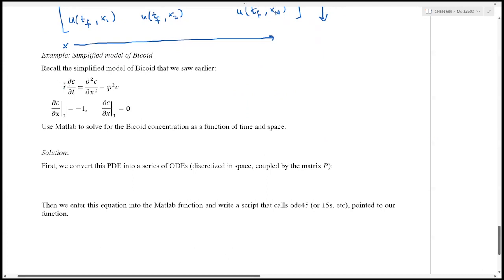Now, because you don't have a 0 here, you get a parameter multiplying this first derivative, and that would be the timescale tau. So tau, because of the way we did the non-dimensionalization with the Thiele modulus popping up here, has to be defined as L squared over D, and that would be the timescale of diffusion.